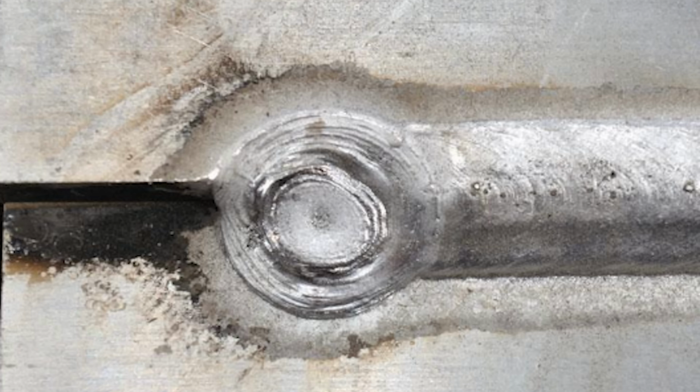How you get around this is you more or less keep walking the cup or moving the arc forward, while slowly lengthening the arc gap to where the arc is no longer as focused. It's a way to get around the issue of just snapping out of it really fast and leaving that defect. Now, if you have a foot pedal with your TIG setup, then what you want to do is slowly taper the amperage out and give that crater pipe a time to solidify. And along with pushing more filler at that moment, you will prevent a hole as well as cracking in that crater.